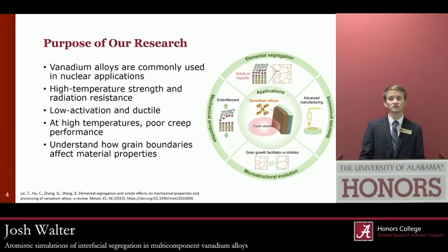However, they do have some weaknesses. For example, at high temperatures, some vanadium alloys will tend to have poor creep performance after being under load for long periods of time. Eventually, the material will start to weaken. Obviously, this is not ideal, so we're working to develop better vanadium alloys that will perform better under these sorts of situations. And then we're also working just in general to understand how grain boundaries can affect material properties.